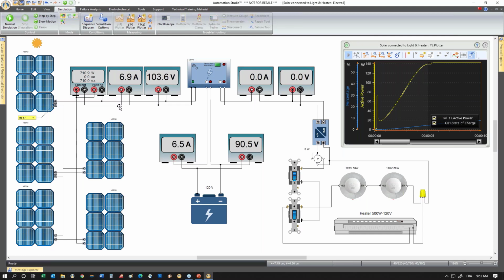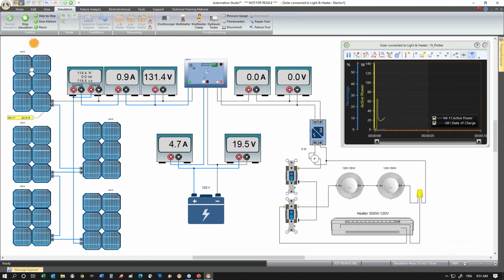So you see I have my solar panels that are connected. When I start the simulation, the power of the array is supplying the battery. It's charging the battery at a certain rate. Even if I trigger this, there's no power provided to my load, because I defined in the PVM that only after 110 volts will I supply the current to the system.